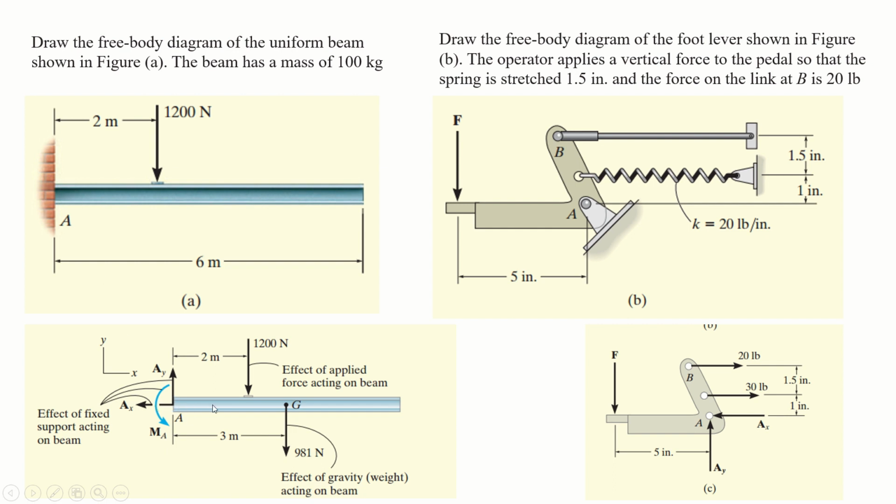You can see here its AY reaction is given in the upward direction. It is given upward because the action forces are downward, so the reaction force will be in the upward direction. The reaction moment is given in the anti-clockwise direction because the moment produced by the action forces is in the clockwise direction, so its reaction will be in the anti-clockwise direction. And lastly, the AX reaction is given in the x direction.